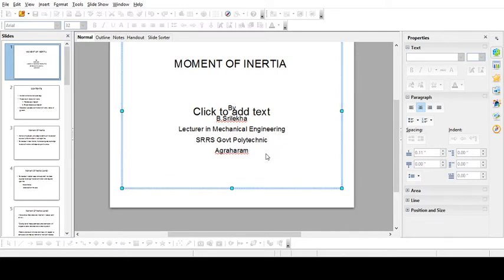Now the second moment of inertia about the y axis, Iyy, is equal to integration of x square dA. So if you want about y, you need to take the distance from that y axis towards the part where the centroid is acting, in terms of x. So it is Iyy equal to integration of x square dA. Likewise, we'll be taking.